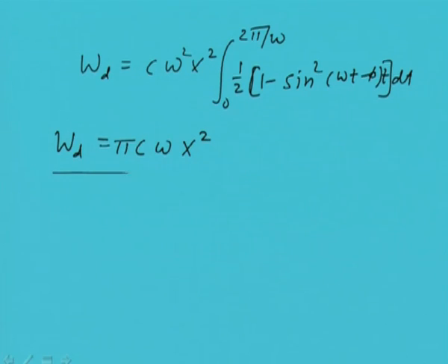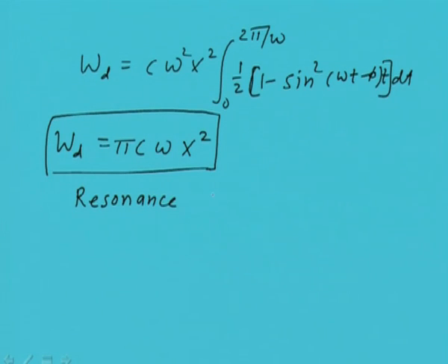so this is the energy dissipation in the forced response, especially when we are talking about the resonance. At the beginning lectures I have already explained what is the resonance. When the frequency of excitation is equal to the natural frequency, we have a resonance. And if you substitute this in this expression, which itself is root k by m, that is the undamped natural frequency, and so this will be substituted here.